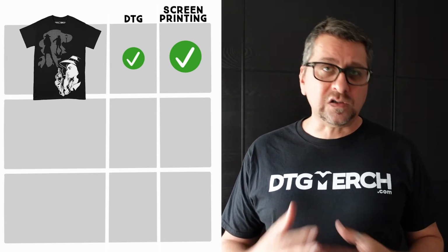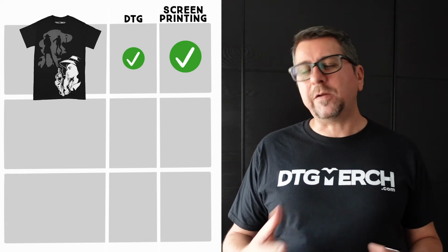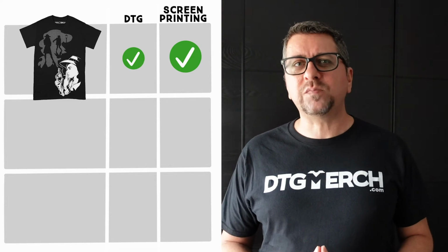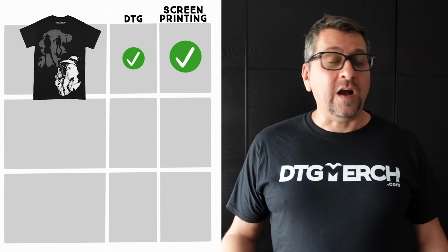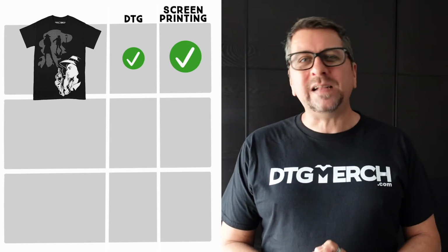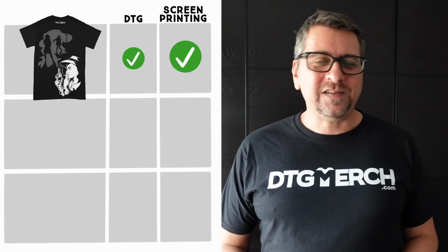If it's a custom piece, choose direct-to-garment printing. If it is a large run, screen printing is most likely more cost-effective. However, we believe that screen printing is just a tiny bit better to print this kind of designs. You see, with DTG printing, large solid areas are a little unforgiving, and you will immediately see any print imperfections, like missing nozzles that can cause fine lines on the print.